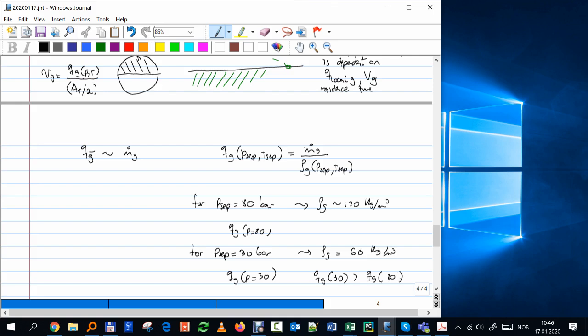Because I'm operating still in plateau, so I have the same mass flow for both. I have the same standard rate for both. Therefore, what I'm doing, I'm changing density, which will be lower for one case, and then this one will be much bigger for that case. And that will affect everything. Residence time, you have to verify that that separator works. Maybe you have to change something in the separator, revamping your facilities. You have to make some investment, and that's not always feasible. It will be like almost evaluating a new plant.